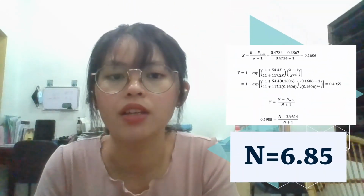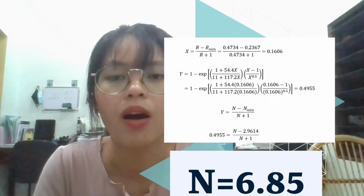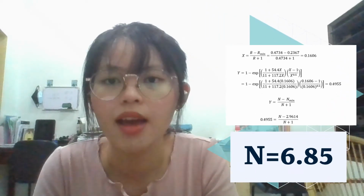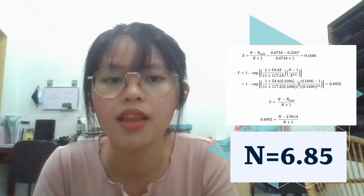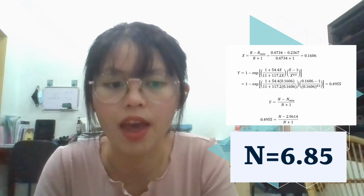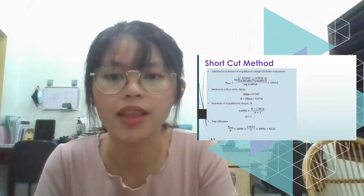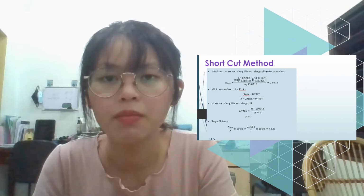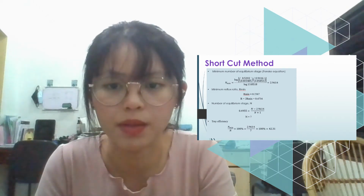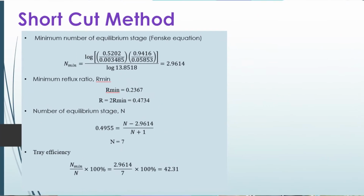Linear correlation is applied to determine the number of stages, and after performing the calculation on my right hand side, the number of stages N is 6.85, which is approximately 7. The tray efficiency is then calculated by using the equation N min over N times 100%. Hence, the tray efficiency in T102 is 42%.